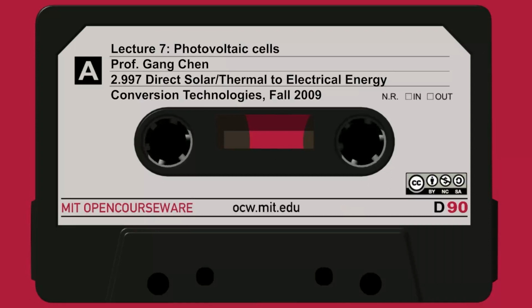And then you look at this: EC minus EF is growing. Here on the N side, EC minus EF is here. In the space charge region, it's growing larger. So the electron is carrying more heat per charge. It's carrying heat out of the space charge region. That's why the space charge region is actually cooling.